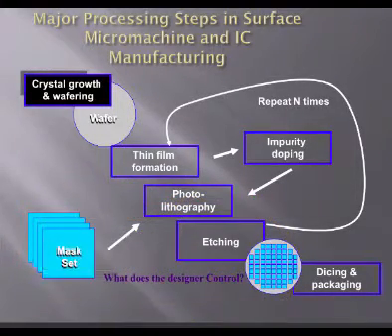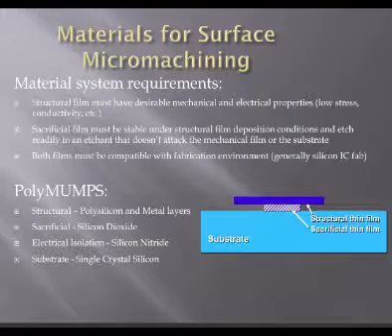But you can see there's a lot of complexity and a lot of detail that you have to be aware of. And, you know, as a technician, you might just be working in thin film, okay? But at least you'll know that if I make my film a little too thick and I'm making a MEMS device, then that spring is going to be a little stiffer because it's thicker. So now my resonators won't work. So then you'll understand, gee, I have to really maintain thickness control. So you get the idea, right? There's reasons why we have to do these things.